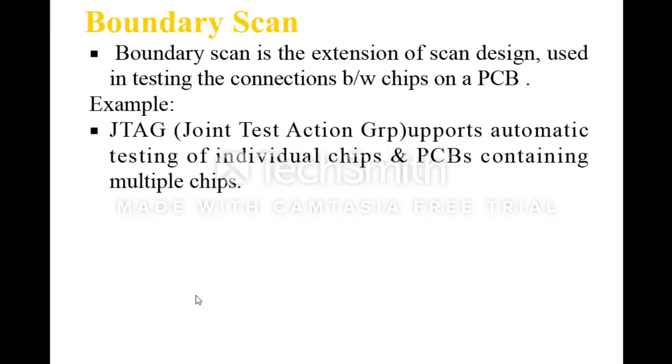Another kind of DFT is boundary scan. It's an extension of scan design used in testing the connections between the chips on a PCB. An example is JTAG, which supports automatic testing of individual chips and PCBs containing multiple chips.